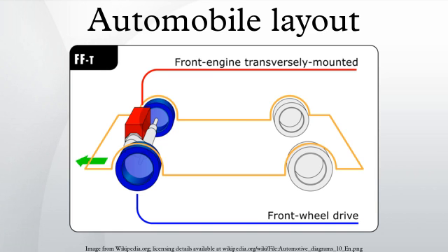The 2005 Jeep Hurricane concept had an all-wheel drive layout that featured two V8 engines powering a single driveshaft, with a gearbox mounted in the center of the vehicle. The gears connected to two additional driveshafts, one on each side of the vehicle, that delivered power to the wheels via driveshaft joints. This was designed in order to accommodate the vehicle's unique steering system.